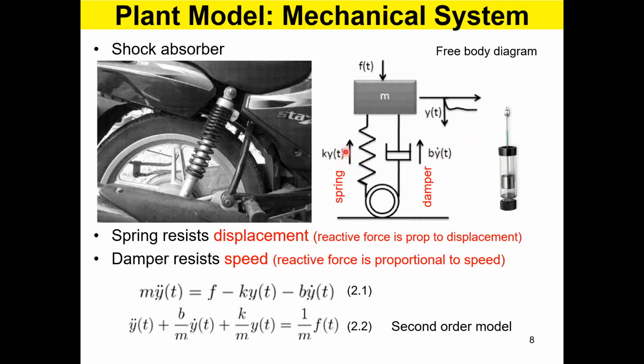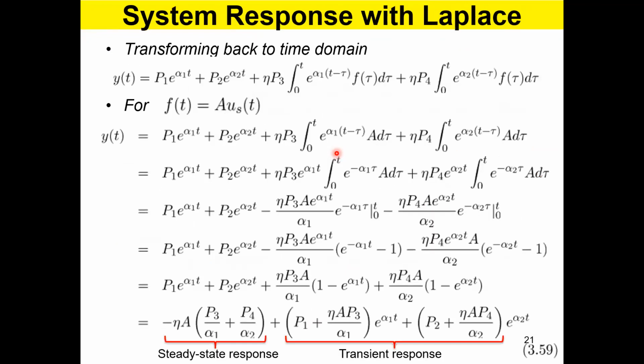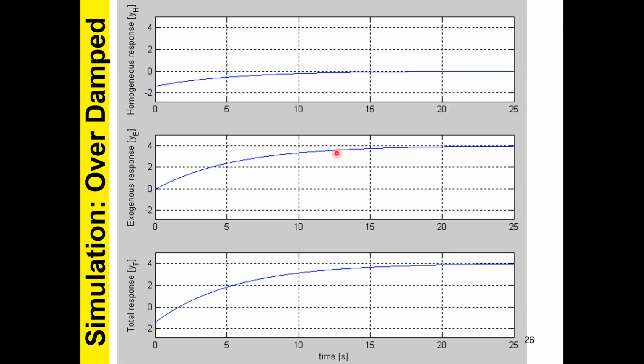Spring is different. Spring produces a force wherever it is. There's only one position, the zero position, where the spring does not produce any force, but at any other position, up or down, it produces a force because the force comes from the deflection. Now you can tell me what's going to happen here. After settling down, there's no motion, there's no velocity. Therefore, the damper is not producing any force. Take the damper out, and it is a 500 Newton force balanced by the spring.